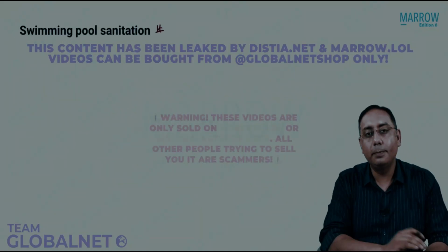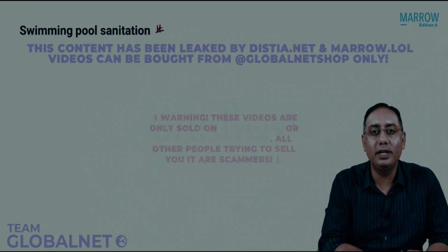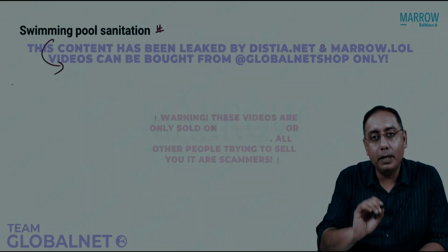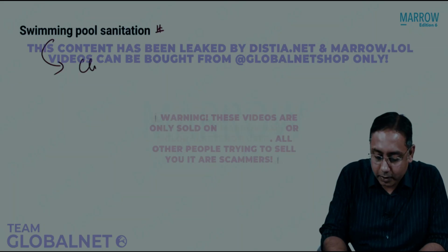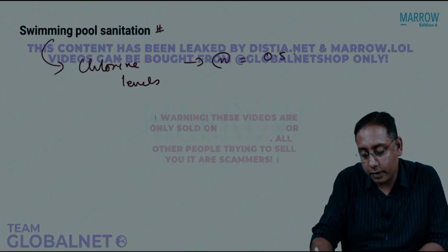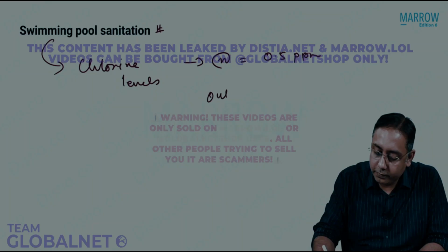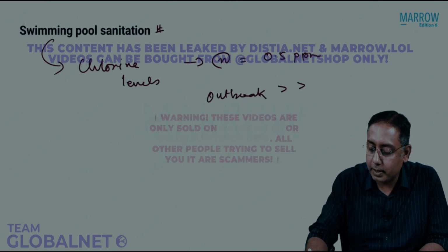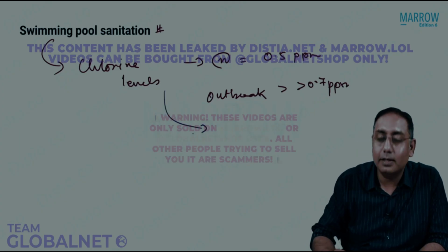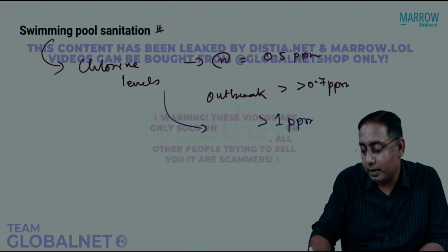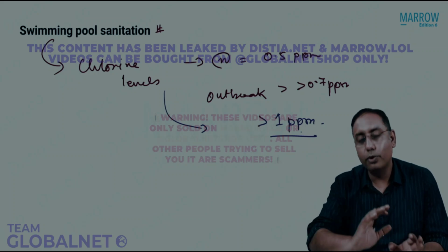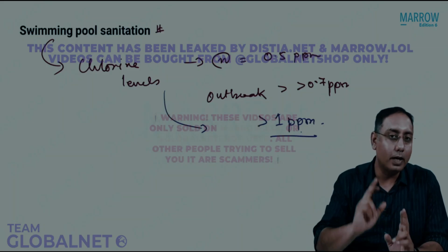Next topic is swimming pool sanitation. So when we are going to swimming pools, we need to be sure that the swimming pool water is safe, yes or no? So how do you ensure? Beta, the swimming pool sanitation, first element is about the chlorine levels. Chlorine levels in normal drinking water is 0.5 parts per million, we discussed. In outbreak phenomena, they are more than 0.7 parts per million, we already discussed. In swimming pools, the chlorine level should always be more than 1 part per million. They need more chlorine because a lot of people will be there, a lot of infections can happen. So more chlorine, more people, swimming pool. Remember, 1 part per million.